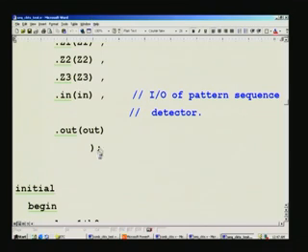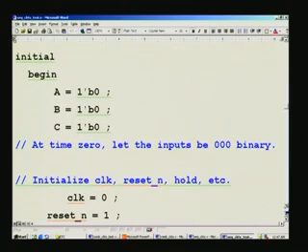And we have completed the listing of IOs here in the instantiation, and that is why we have the end here. And once again we have initial, and I do not have to go step by step in this. It is sufficient to say that all the inputs that we need for testing this whole sequential circuit will appear one at a time.